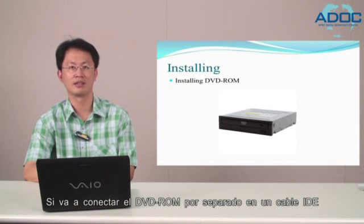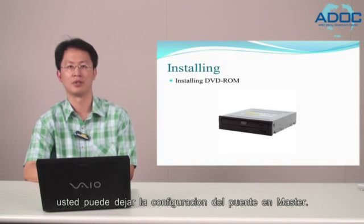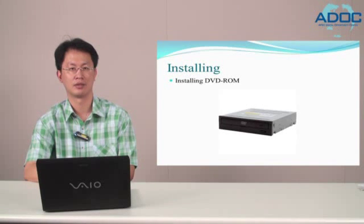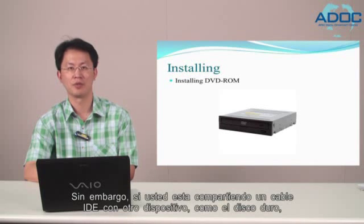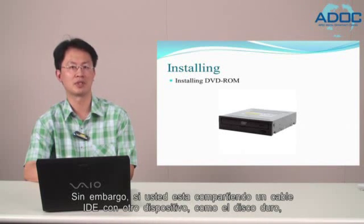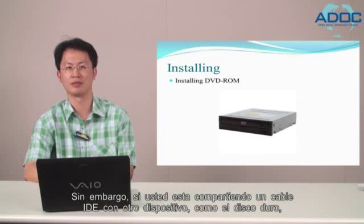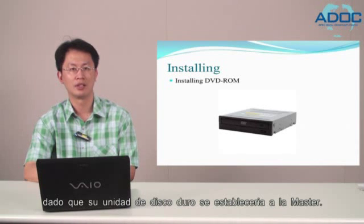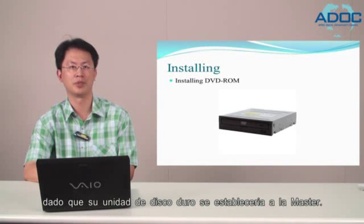If you are connecting the DVD-ROM on a separate IDE cable, you can leave the jumper setting to master. However, if you are sharing an IDE cable with another device like an HDD, then you will have to set the jumper to slave, as your HDD would be set to master.